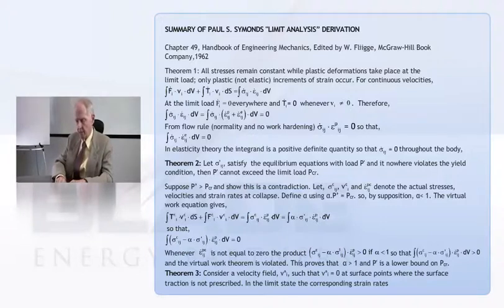If you remember how the yield surface looks, the yield surface in the pi plane is circular, and the plastic strain increment points radially outward, then you have to conclude that this guessed stress field can't be violating the yield condition. It can satisfy the yield condition, but it can't exceed it.